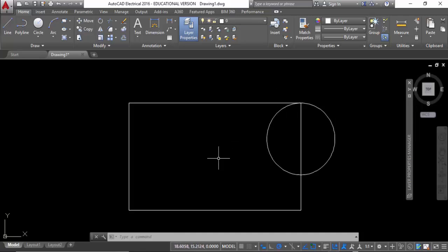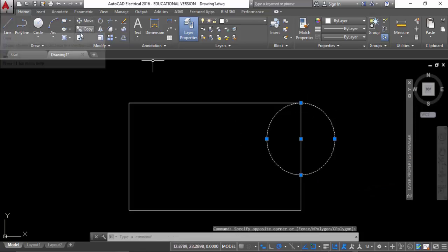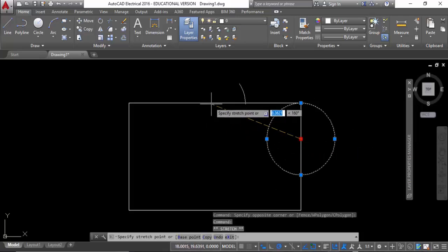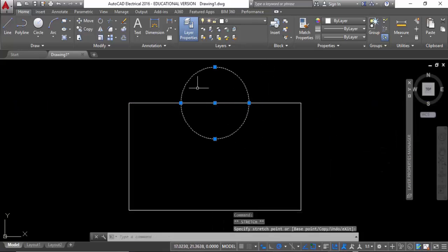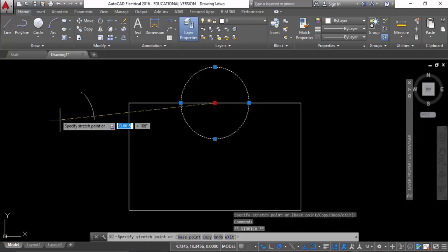That's a standard move. Now if I wanted to move without utilizing the tool, so sometimes you are in a bit of a rush and you needing to get the job done, you can select the object, but what you would have to then do is select the center little point that is brought up, and then go through to a snap point. You can then place that in place. Alright, so if I'm wanting to move it, I can do that.